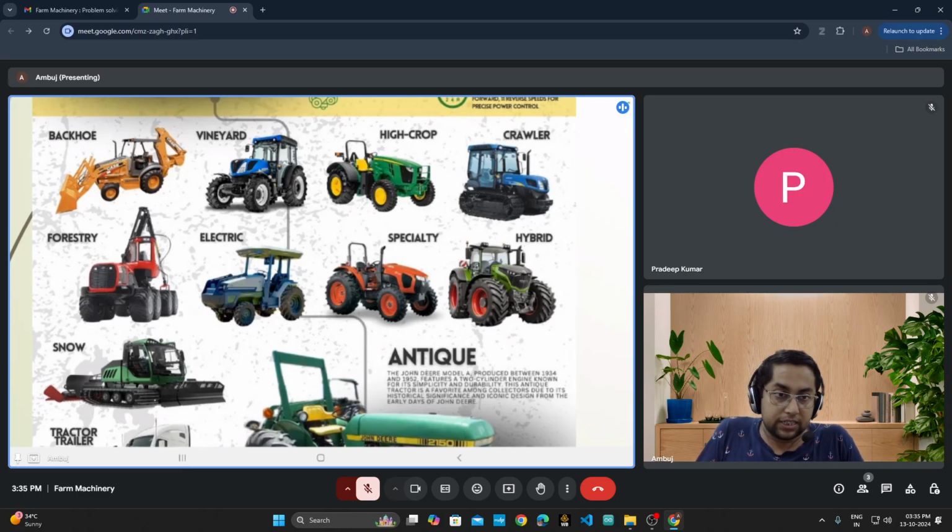Four motors are there on different wheels, and current is provided through batteries. The primary source of propulsion is those motors only, and those motors are planetary gear motors for high torque as well as low power consumption. The current state of the art motors are BLDC motors. You must have seen those motors in your e-rickshaws, as well as in your e-skateboards. Those motors are very common. BLDC means brushless DC motors, brushless direct current motors.